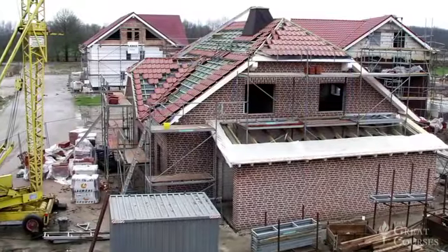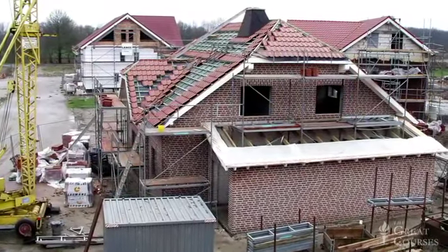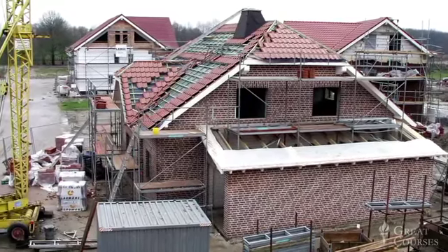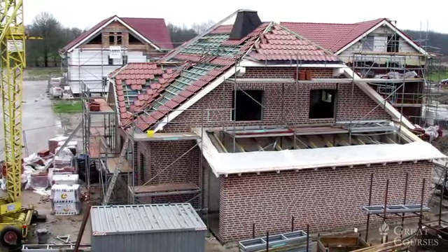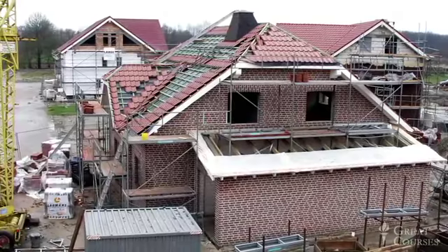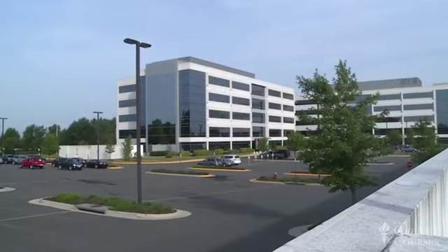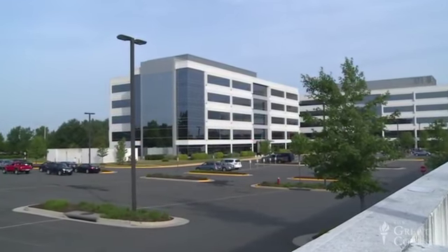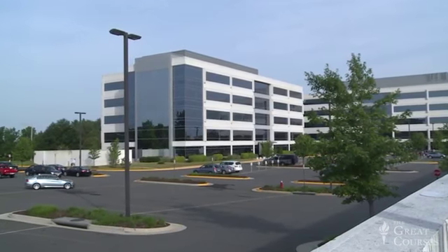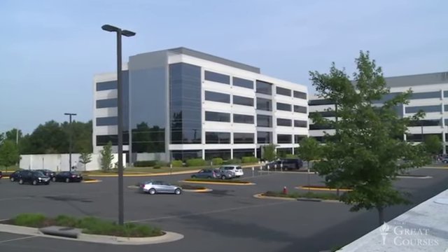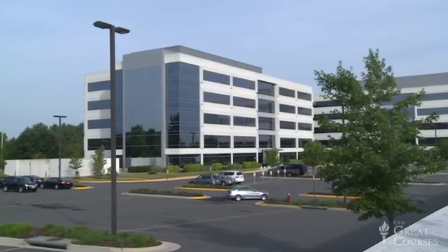If we look beyond our borders, we'll see that lightwood framing never really caught on in Europe, probably because timber is not as plentiful there. Thus, modern European residential construction is still largely of the bearing wall type, using brick, concrete block, or ceramic block walls. And if we look beyond residential construction, we'll see that the structural concept embodied in the heavy timber frame is present in most modern commercial buildings.